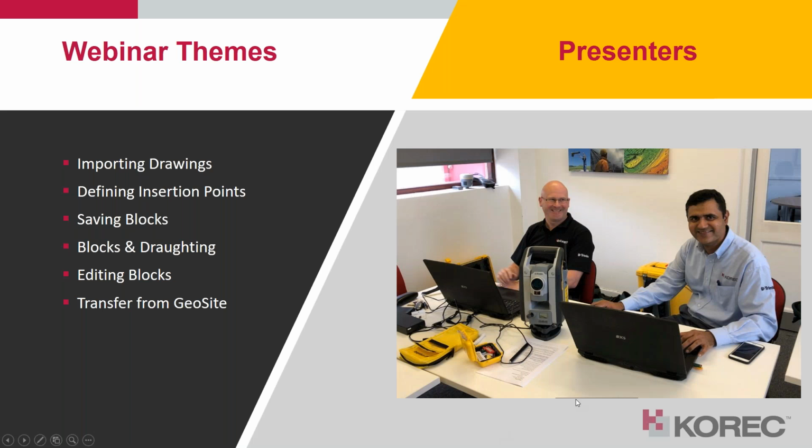My name is Richard Selby, and the themes that we'll be looking at within the webinar are bringing your drawings into TBC, drawings that would contain the blocks that need to be set up, how to create those blocks and define the insertion points for them, so we know that when they're drawn freehand within Trimble Business Centre or used with a code library to draft topographic surveys, how they relate to the field survey points.